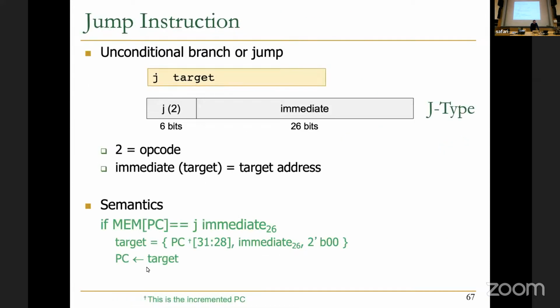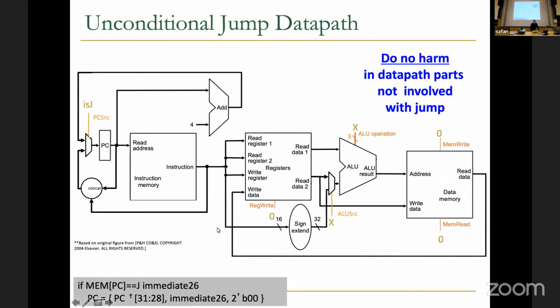If we go back over here, PC is really the incremented PC. So you may get the wrong top 4 bits. So you should really do this one. Get this output, PC plus 4, and concatenate it with the 26 bits coming over here, and you should really not get this PC over here. Make sense? Basically, do what the instruction set tells you to do. That's the moral of it.